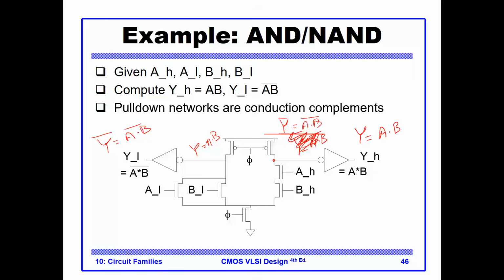So at this point, it's easy to produce the NAND by just simply having this PMOS inverter for the pre-charge and the evaluate, and a stack of two NMOS transistors, one connected to A and one connected to B. There you have it. You have here A, B, NAND. Okay, well, how then can I produce A, B here with just a negative logic here?